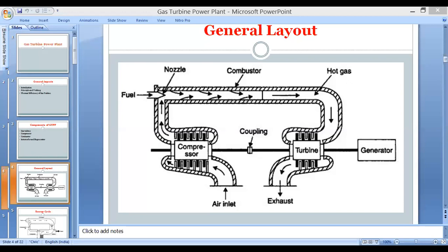In the energy cycle, the air brings in a minute amount of energy. Second, important point, the compressor adds a considerable amount of energy. The fuel carries the major input to the cycle. Next, the sum of fuel and compressed air energy leaves the combustor to enter the turbine. In the turbine, a small part of the entering energy goes to useful output, the larger part leaves to exhaust. That is an important statement in our energy cycle.